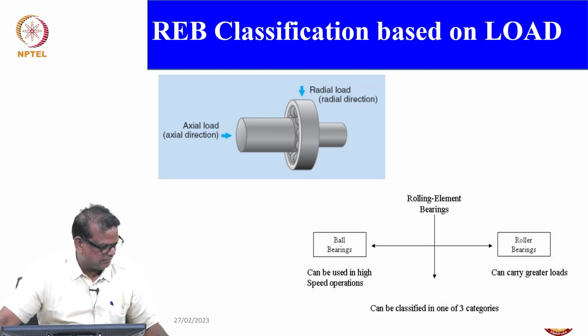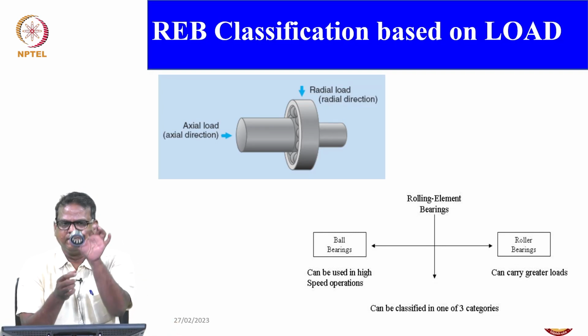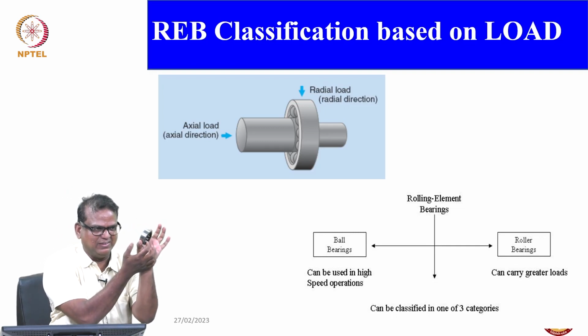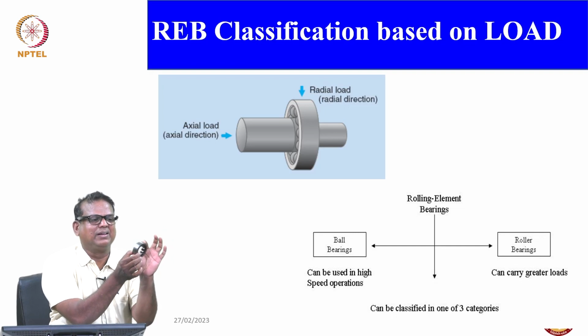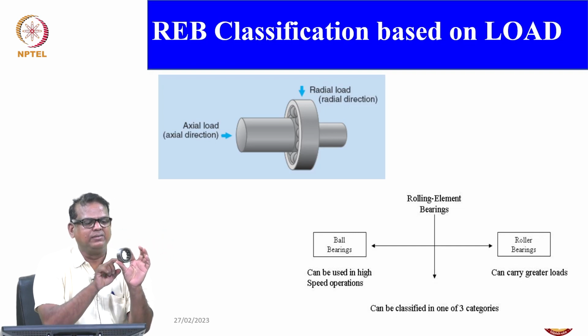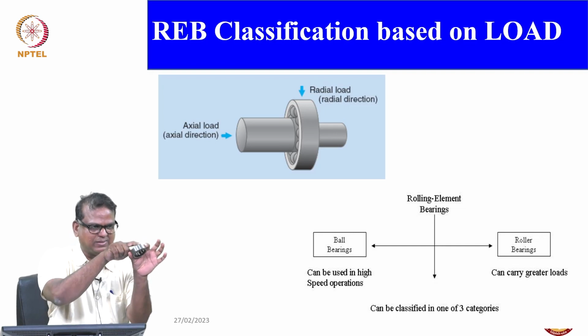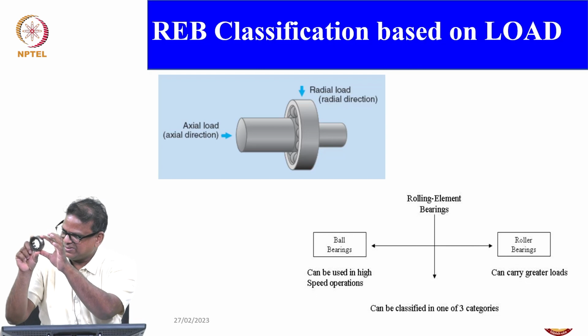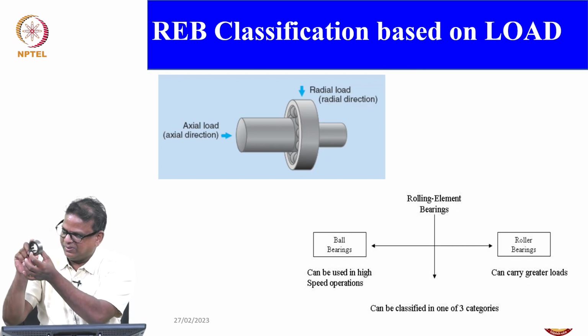And this is another information. You can see that. Can you see, this is a roller bearing, cylindrical. So, again you have an outer race, there is an inner race, and they are placed with a nice cage arrangement. You can see that this is your cylindrical bearing for higher load application.